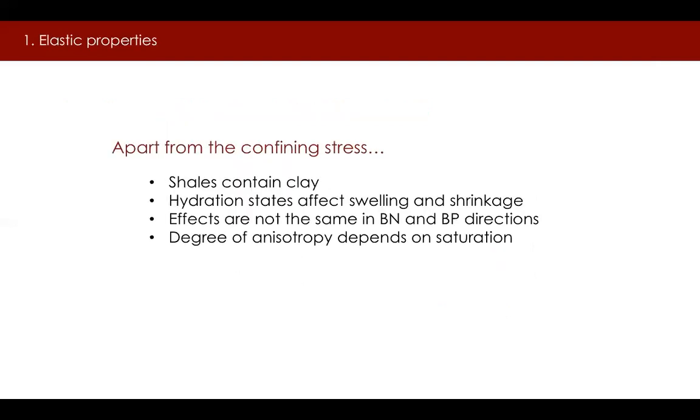We know that the stiffness moduli of geomaterials depend on the confining stress. But shales contain a significant amount of clay, so their elastic properties also depend on the state of saturation of the rock. Because the orientation of clay particles in a shale is partly responsible for its anisotropic behavior, the presence of water affects the properties of the rock differently in the bed normal and bed parallel directions, denoted as Bn and Bp respectively.